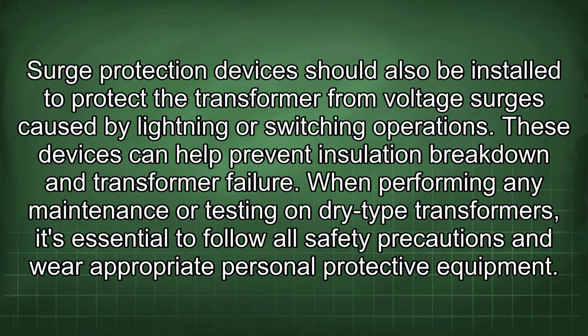Surge protection devices should also be installed to protect the transformer from voltage surges caused by lightning or switching operations. These devices can help prevent insulation breakdown and transformer failure.